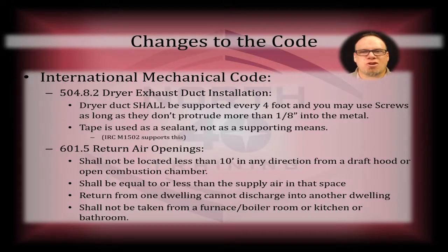504.8.2, dryer exhaust duct installation. Dryer duct shall be supported every 4 foot. That's pretty straightforward. And you may use screws. Oh my goodness, that's your change right there. You might be able to use screws on this stuff. Oh wait, there's more to the code. As long as they don't go through the skin of the metal more than 1/8 of an inch into the duct.